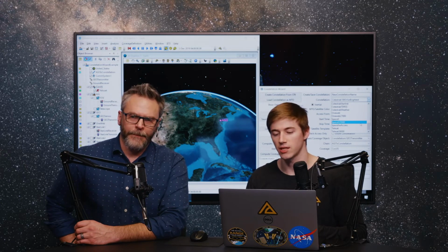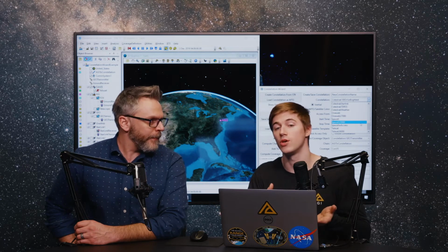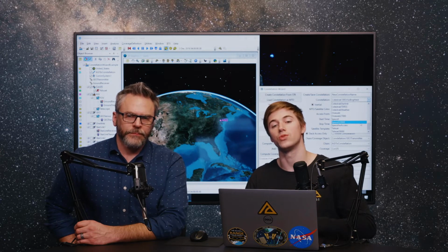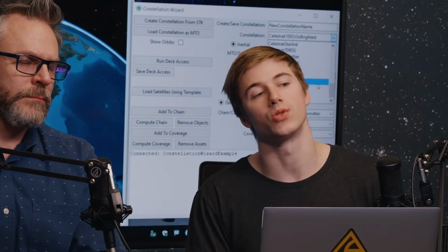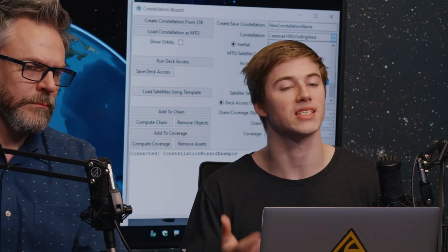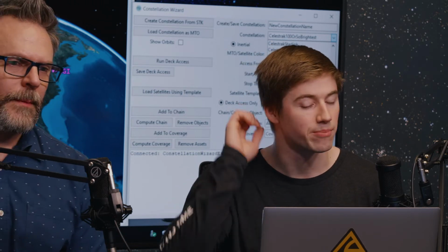Yep, that's exactly right. So the way this constellation wizard works is it brings them in first as an MTO, a multi-track object, purely for visualization purposes. Then after that, we'll do something called deck access, which will allow you to say, hey, I only want these satellites that are currently overhead or in the next hour or so, and bring that subset in for further analysis inside STK. So what you did is a streamlined interface to easily go get the data right off of CelesTrak and pull it right into STK.